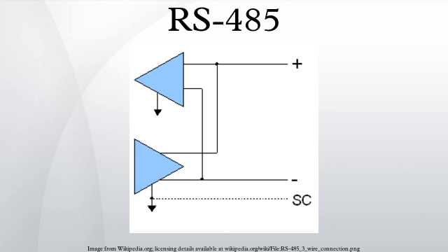Connectors in this case are 8P8C/RJ45. Although many applications use RS-485 signal levels, the speed, format, and protocol of the data transmission is not specified by RS-485. Interoperability of even similar devices from different manufacturers is not assured by compliance with the signal levels alone.